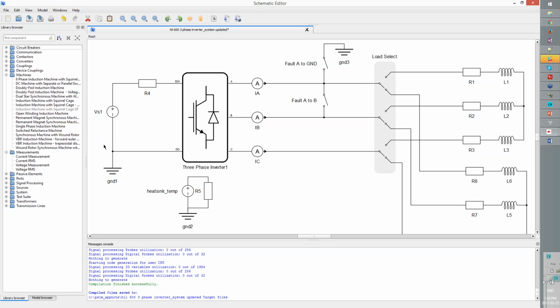And actually, that's a nice segue to some of the other advanced functionalities. PSIM has recently rolled out InstaSpin support for the F28069, so you can do code generation around the very easy to use InstaSpin platform, and very powerful sensorless control observer from Texas Instruments. And then there's a question about HIL: yes, you can define a mechanical load in with the hardware-in-the-loop system as well. Exactly. So all that can be handled.